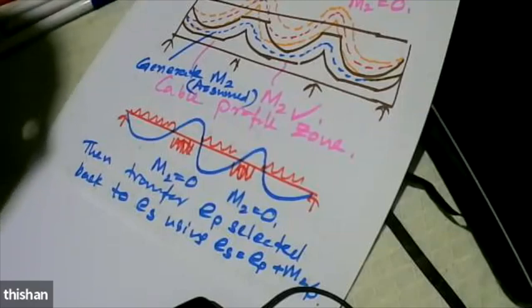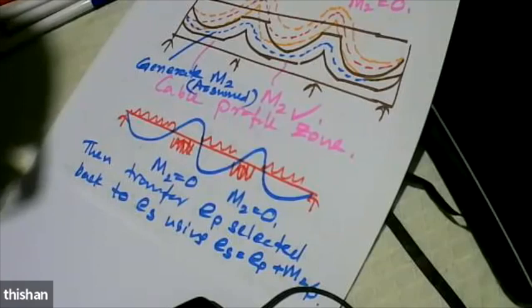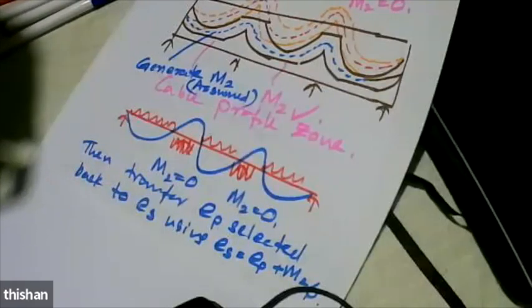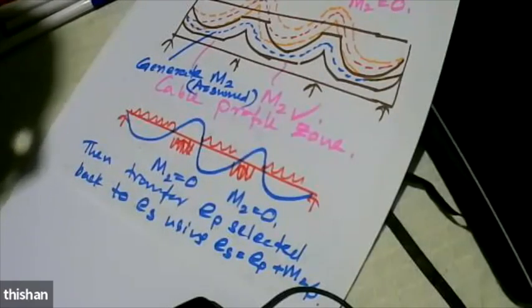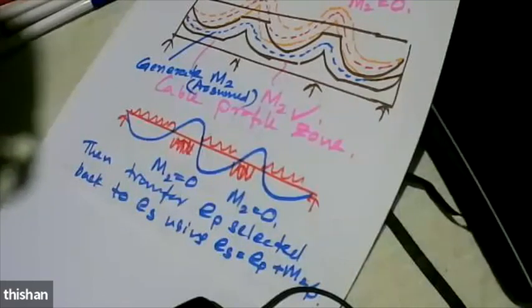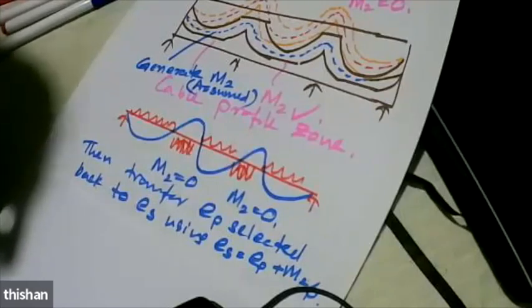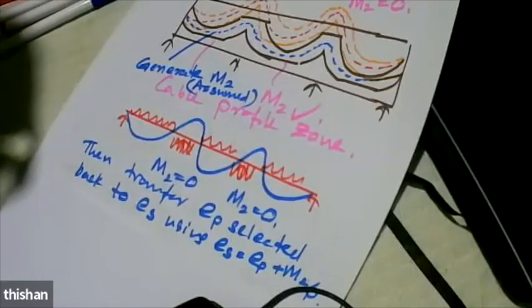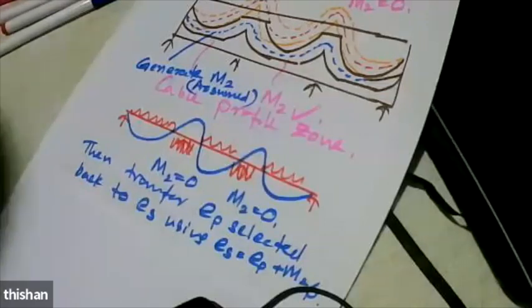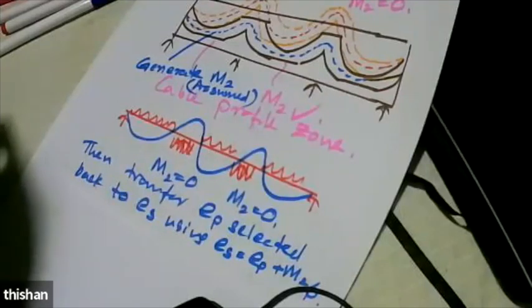So next time I can actually show you how this method can be used to design a continuous pre-stressed concrete beam using a spreadsheet. Basically, within 2-3 hours, you can design a continuous bridge using this method, because we are doing all the calculations only in one direction. We are not doing any trial and error calculations, because everything is well set; we are going to assume the values initially and ensure those are generated.